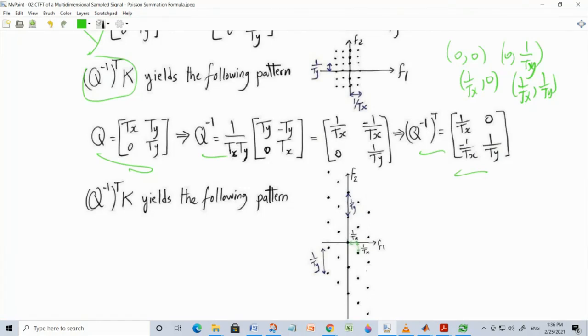The overlaps do not necessarily mean that the sum, the periodization, will explode to infinity. It may also be finite, and this is actually the assumption when we periodize: we are dealing with signals in which the periodization is finite for every frequency. But the idea is that there will be overlaps, there will be aliasing, if your signal is not band limited.